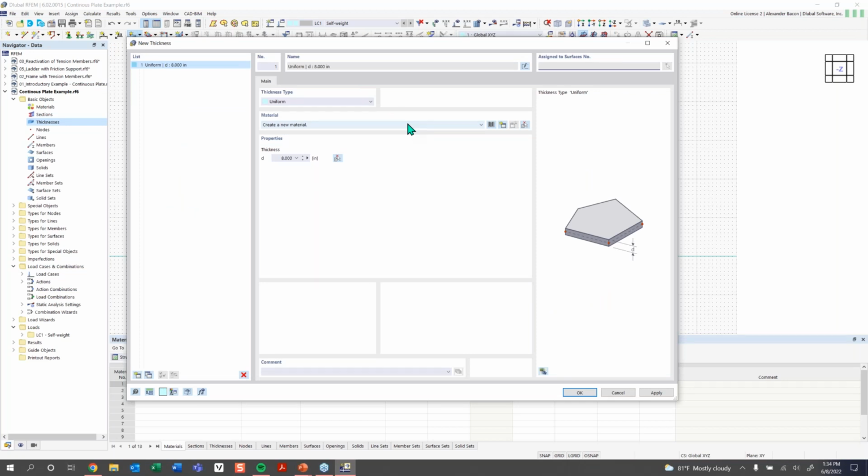So basically with the thickness, you can see what that is defining on the right hand side here. Normally you can think about this as with a beam member or column. That column requires a material and a cross section. So as an analogy, you can think of the thickness as the cross section and then we just need to give it a material. So every surface requires a thickness and material. So we're going to make the thickness of this surface 12 inches.